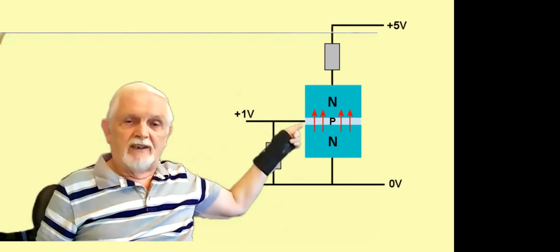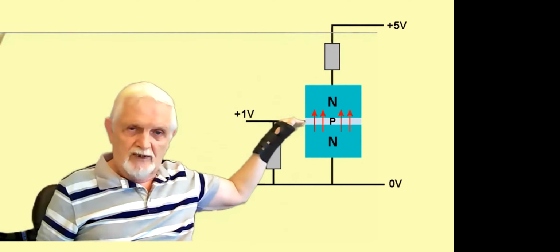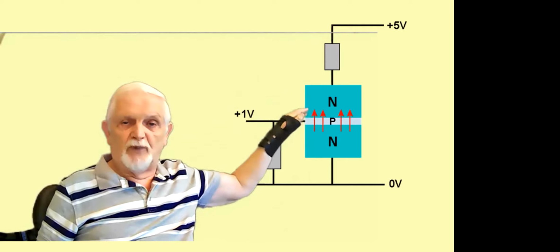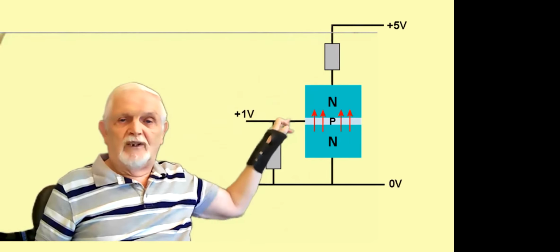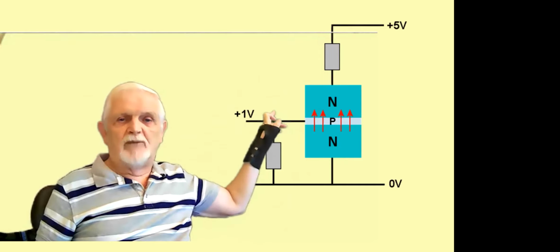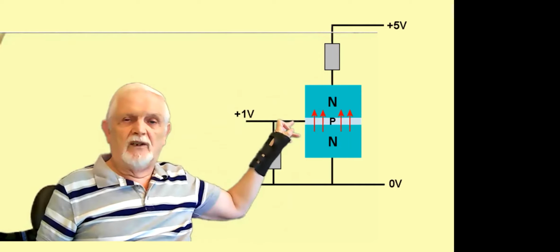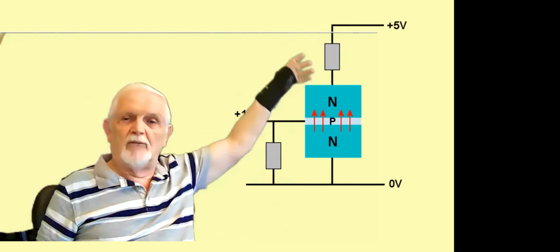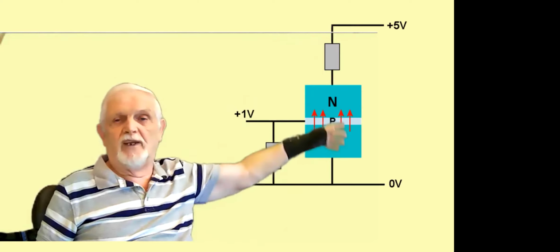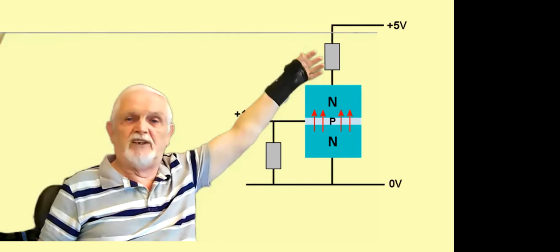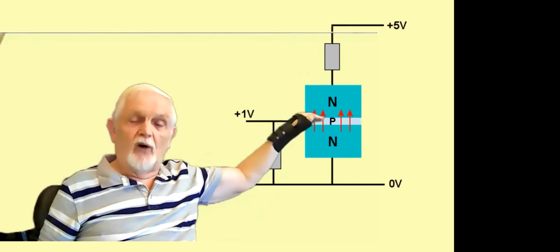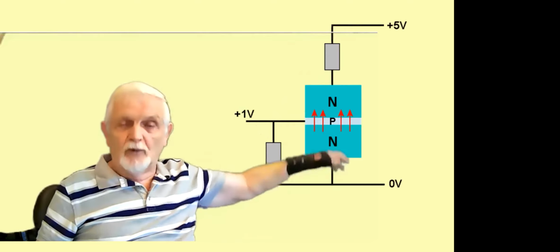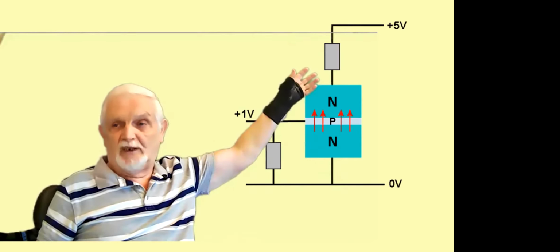So if we change what's happening in this pin by small amounts, we can make it an audio amplifier. So a tiny amount of audio coming in here can result in a much larger amount of current flowing through there and a bigger audio signal to your speaker or headphones or whatever. If we completely drive it on, we get full current and it becomes an electronic switch.